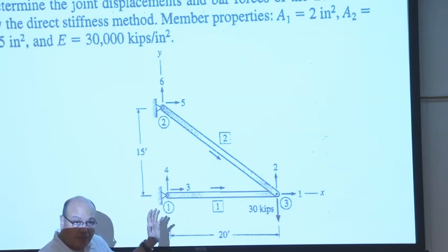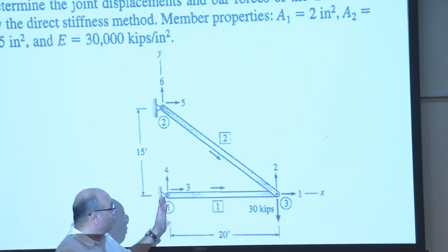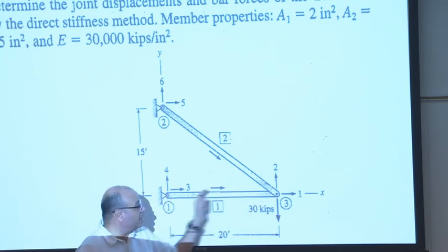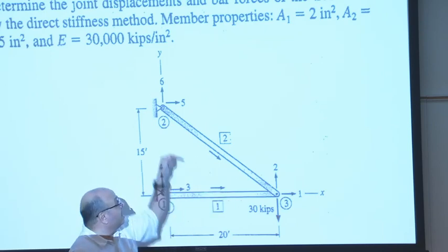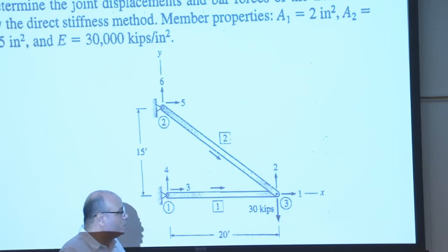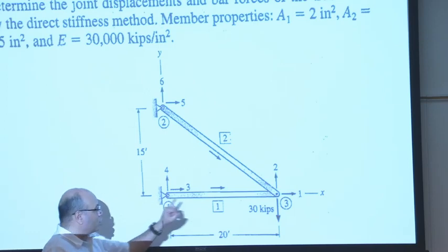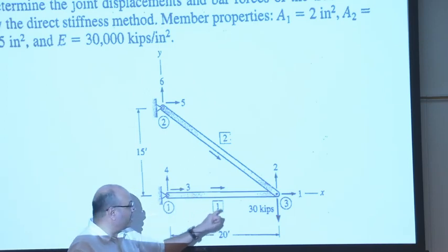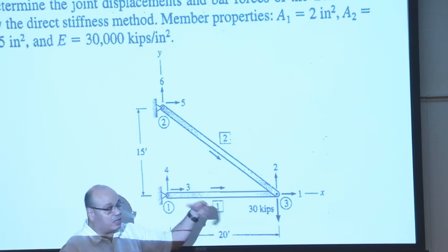And you're going to identify the third thing, what is near and what is far. So from 1 to 3 right here is near to far. So this is the arrow right here from here to here. And this one is near to far. You can put it the way you want it, but let's be consistent later on when we solve the problem. So identifying the joints, done. Identifying the members, done. Identifying the near and far, done.